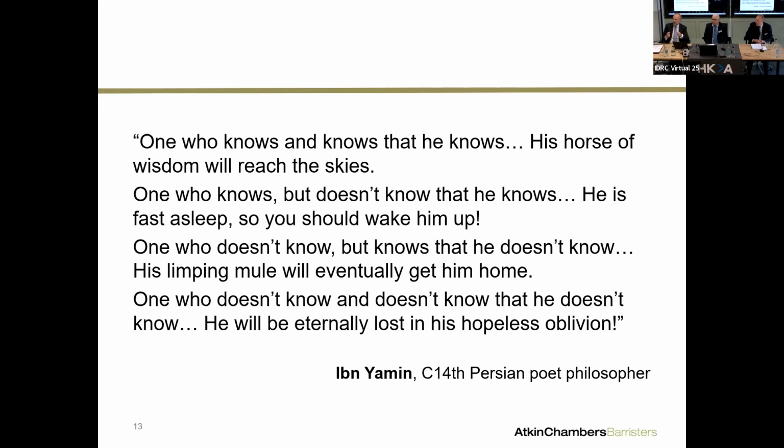That too brings in, as we all know, if you think back to when JCT used to have the nominated subcontract packages, some real issues with who takes responsibility for the choice that's been made of the potential suppliers. Now, clearly, you can try and pass that on by saying, right, here's my performance spec for the fuel crane or for the grate or for the ash systems. But if it turns out that Kone has been chosen and their grab isn't working properly or doesn't lift, or the cycling time on the crane isn't sufficient to get enough waste into the pits, who takes responsibility for that? If the employer said, I want you to design and build the whole thing, but I want you to use Kone. So it's a hybridized thing.